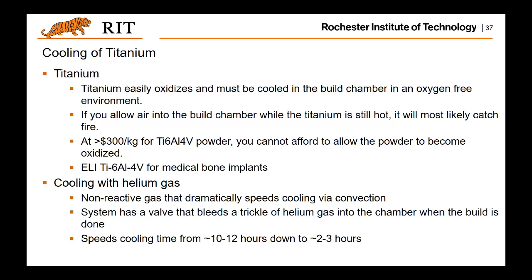Especially the powder material, which is really easy to explode. For the sake of safety, it is prohibited to introduce air to the build chamber when the temperature is still high. So that's the critical thing you want to keep in mind.